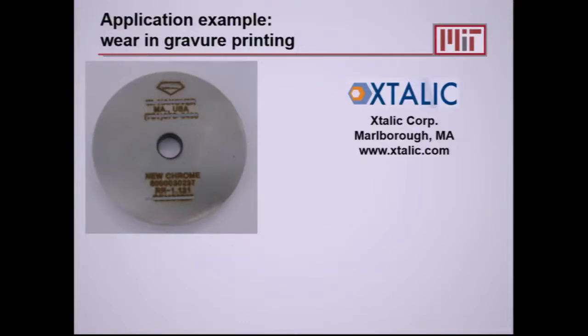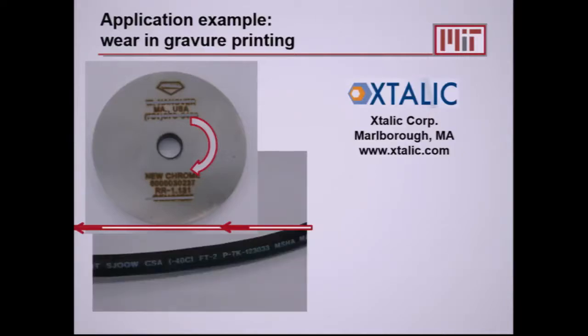This is what they call a gravure printing wheel. Okay, so this thing is about yay big, and it has embossed lettering on the outside of it, and it is going to be used to print some very unexciting information by putting ink on one side and transferring it in a rotating mode against a medium here. This guy is used to print the lettering on the side of electrical cables. So every electrical cable around us has this on it. I'm looking at it right here. This is the guy that does the work of putting those letters on.